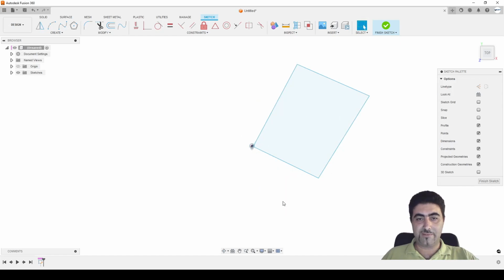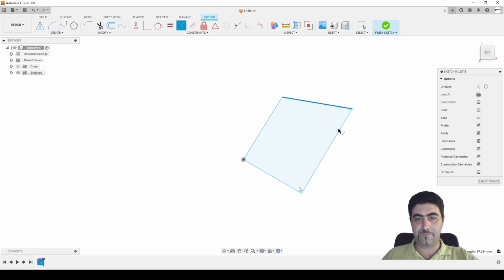We do the same things. Oh, we missed. Okay. So we've done the same thing. We can drag, and these 4 points are completely arbitrary at the moment. Let's start making them perpendicular. And let's see, what if we do the... Okay, so we now have a message saying it's over constrained. You can see it's the exact same wording that we got from the error message in Alibre.